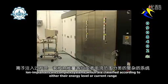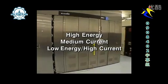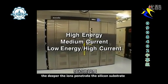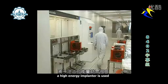Ion implanters are complex systems, which are classified according to either their energy level or current range. The higher the energy, the deeper the ions penetrate the silicon substrate. To create the deep N-well of our CMOS transistor, a high-energy implanter is used.